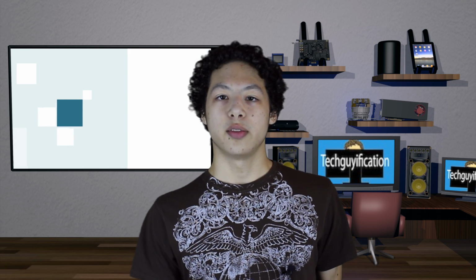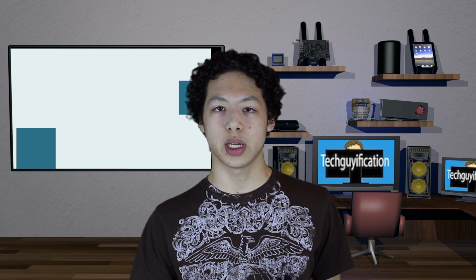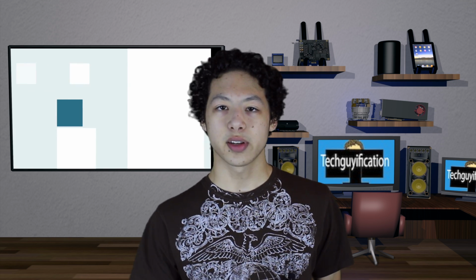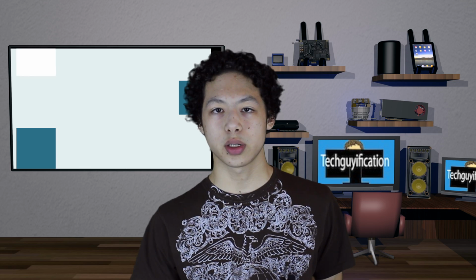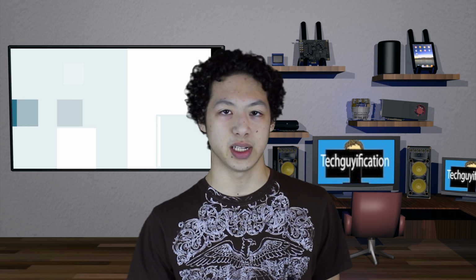So now, go back into front view by pressing numpad 1 on the keyboard and hit Control R. So now move your mouse until you get a purple line vertically up and down the object. You can left click it once to accept it, and then you can drag it left and right, so drag it to the right as I've done, and then hit left click again to finalize it.